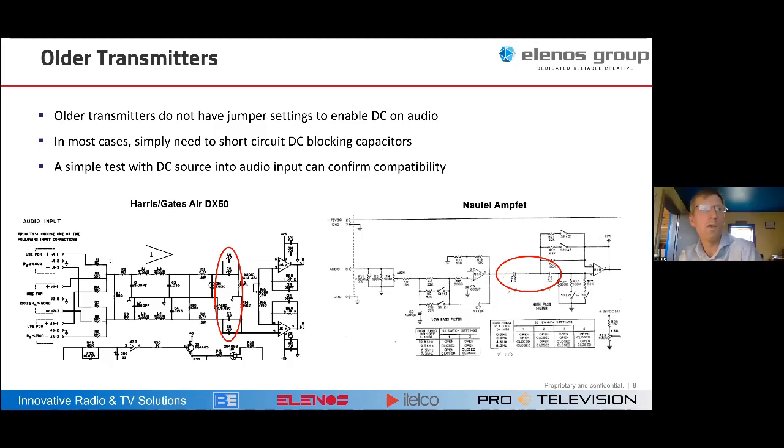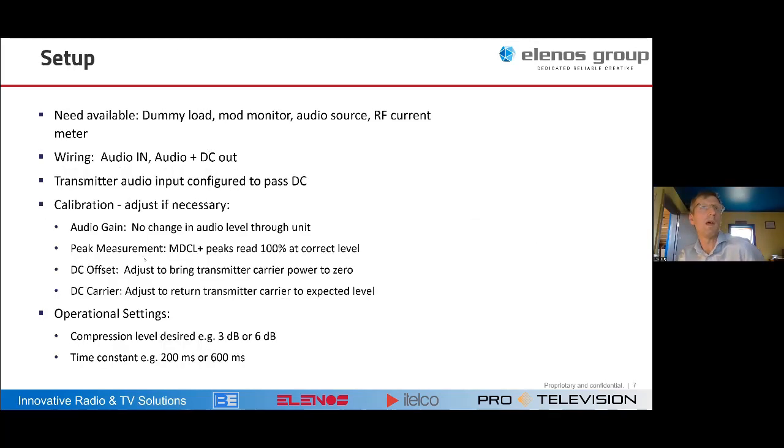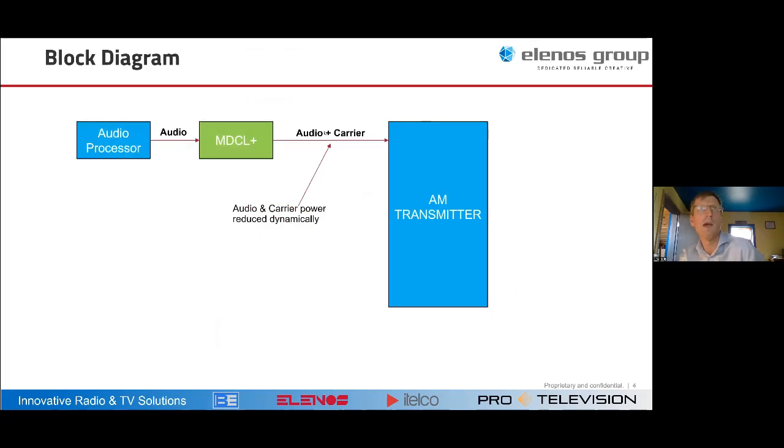Well, the way it works, just backing up a little, you have an audio input on your transmitter now, which is differential. It's 2 wires, right? When you install this system, those 2 wires are going to carry audio as they currently do, but at the same time they're also going to carry a DC level. It's not a separate wire. We run audio plus carrier on the same differential pair that you currently have for just audio.